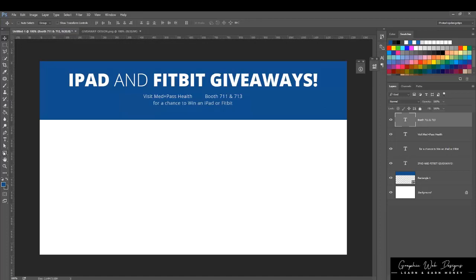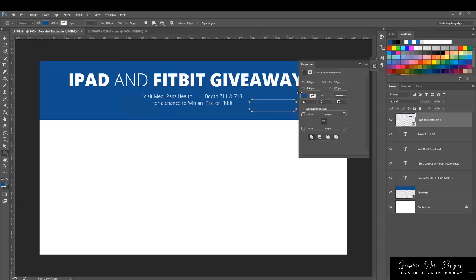In the tools panel, make sure you select the shape tool, then right click on your mouse to see these options. Select the rounded rectangle tool, and with that selected, I'm going to draw a rounded rectangle like this. After drawing, you will see a pop-up dialog box. This allows us to change the properties of the rounded rectangle.